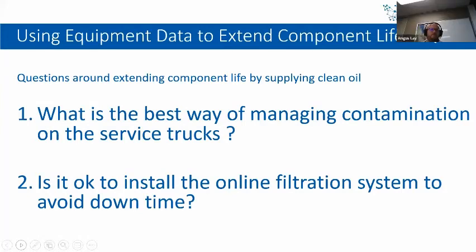The second question we received was, is it okay to install an online filtration system to avoid downtime? Absolutely, yes. A lot of large diggers with large volumes of hydraulic oil have permanent offline filtration systems fitted to remove the contamination that the filtration system on the machine isn't removing, as they're generally high flow, high volume filters.